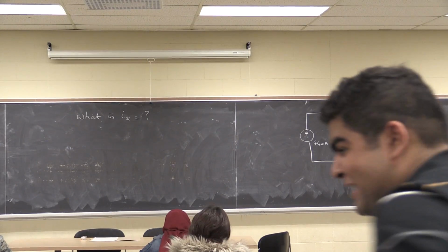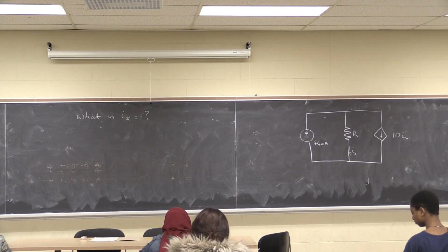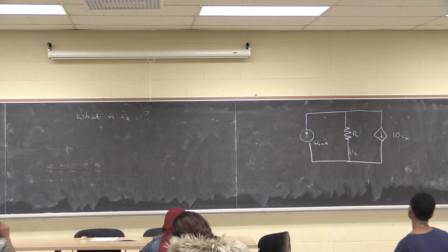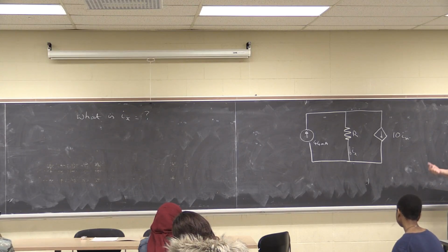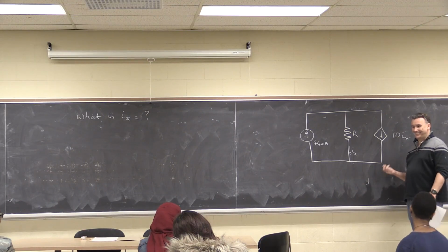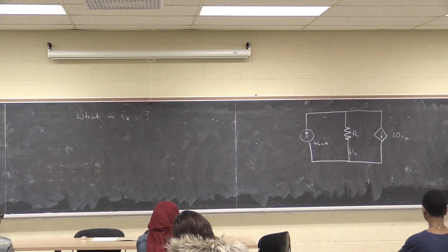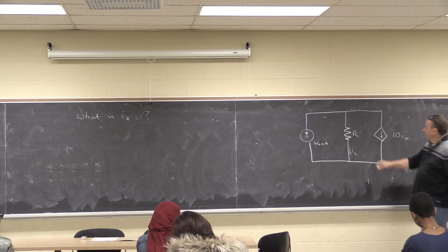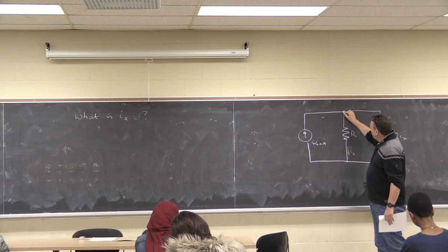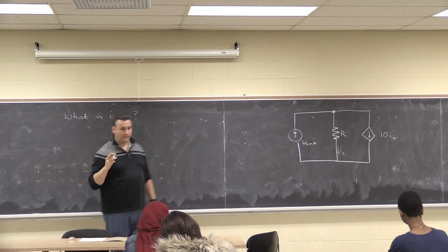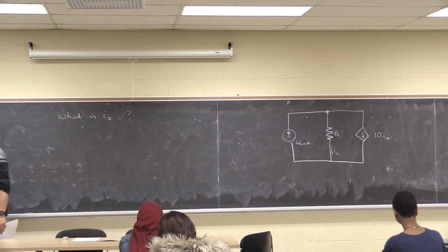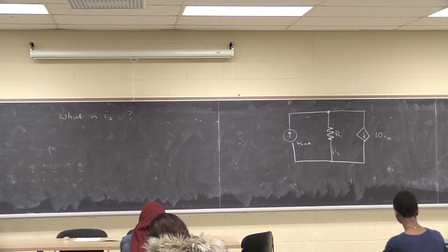Okay, so any thoughts on how we do this? Can we solve this? Well, it's nodal analysis, so let's look at this node here. What does Kirchhoff's current law tell us? The sum of all the currents going into that node equals 0.